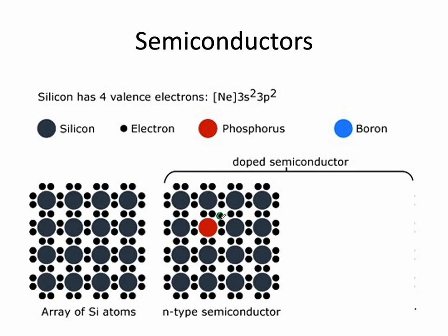And if you look back at the periodic table, you'll notice that phosphorus is one over on the periodic table, which means each phosphorus atom has 5 valence electrons. So now you've got this excess electron in here, and phosphorus is like, whoa, wait a second, I just want my octet. And so what happens? This electron gets passed around the crystal like a hot potato. Nobody wants it, but it's free to move around anywhere it wants inside of the crystal lattice.